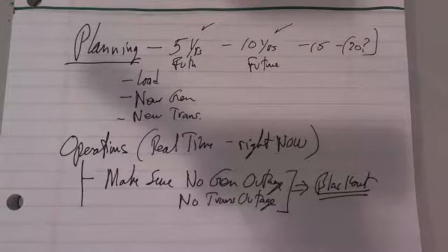Outage number one causes the system to overload, and that causes outage number two, which is a result of that overloading. So now you have two outages, two lines out, or two generators, or some combination.